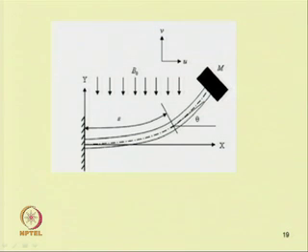So, one has to take this force and couple in addition to the inertia force acting at a distance s from the base of the beam. So, by taking all those forces into account and by applying D'Alembert's principle, one can obtain the equation of motion.